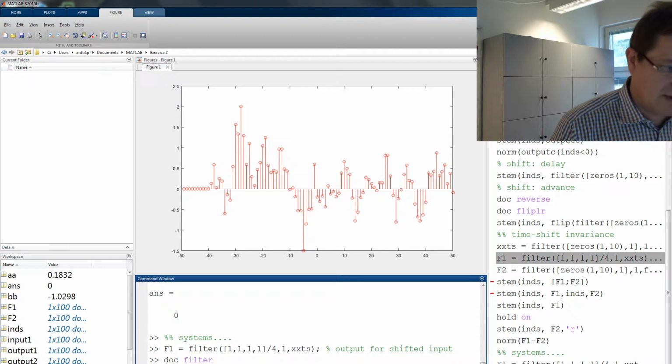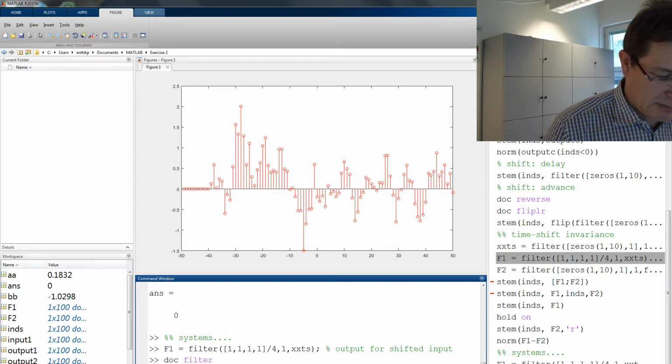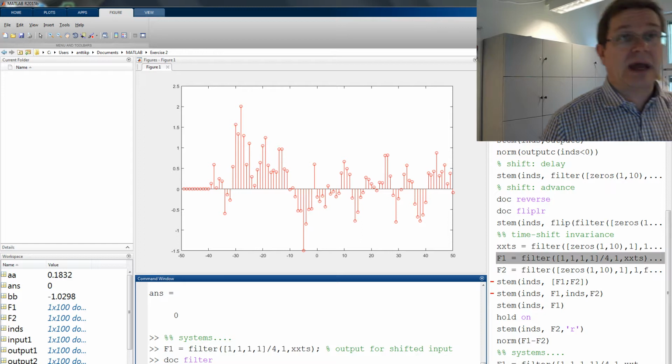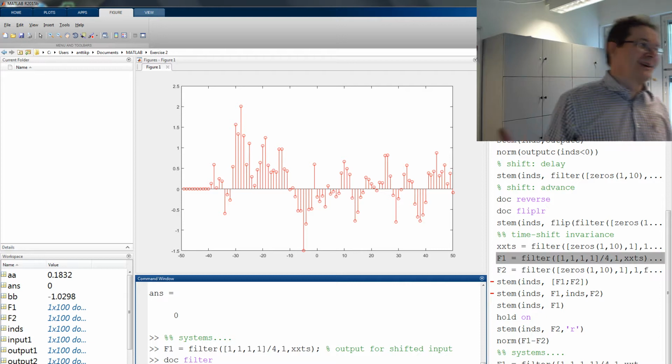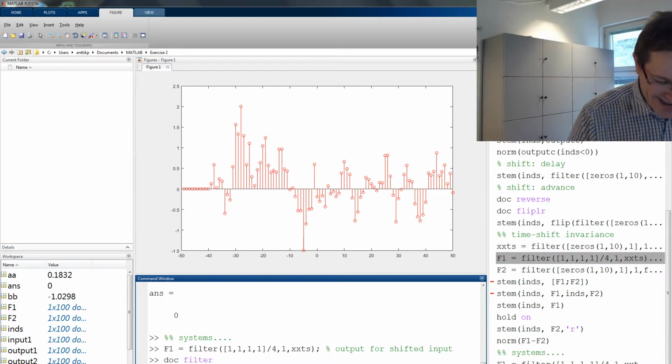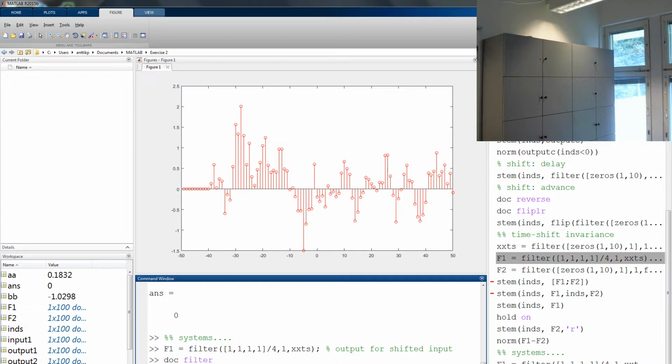Okay, but anyways, first things first. So b equals 1 divided by 4. Actually, if we had a very long running average system, you shouldn't use that. If you have a very long one, you probably don't want to use that many ones there. You will miss one in any case. So ones, whatever the number, the length vector divided by the number, that will give you those parameters.